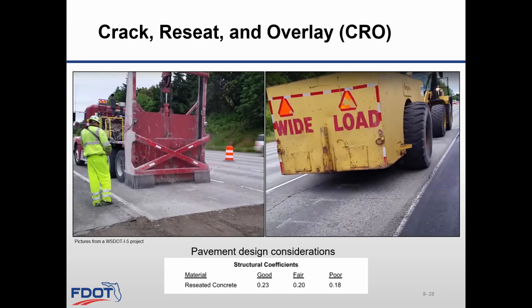The pieces of concrete are broken by a panel breaking machine that drops a heavy weight, approximately 12,000 pounds, guillotine type hammer for cracking the pavement to break the concrete. Then a compactor rubber tired roller, 35 to 50 ton, presses down the concrete onto the existing base to ensure the concrete is seated well into the ground.